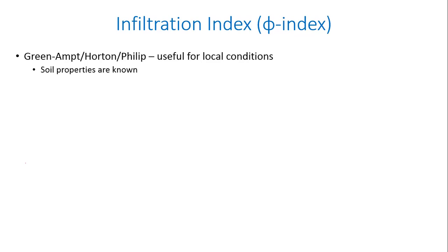I know that the soil that I'm encountering at this point is a sandy soil or a clay soil or silt or whatever it is. If I know all that, then using these approaches, whether it is Green-Ampt or Horton or Philip, it's relatively feasible, assuming that I know the soil properties. But if you're interested in a relatively larger area, let us say you are interested in the whole catchment, then you need some kind of a simpler approach that is valid for an entire larger area. Instead of having knowledge about point locations and how the soil properties vary spatially, you may need to come up with a simpler approach which can be applied for a larger area.